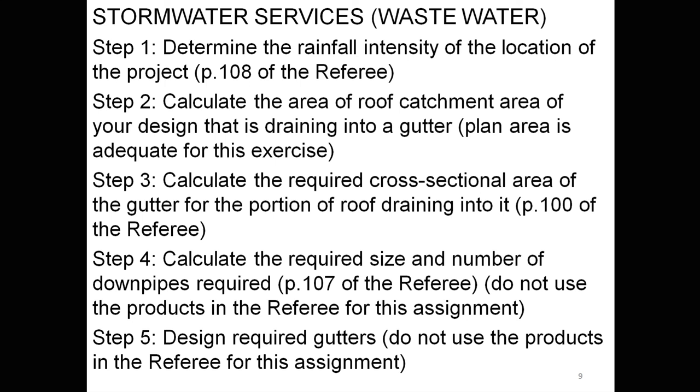I was thinking more in the roof realm up near the gutter. Surely there's an overflow point that needs to be included. No. Especially if it's sitting behind a wall. Put it this way: it comes back to what's going to cause a blockage. You only need an overflow if there's going to be a blockage, because you can essentially design the system where the water will always be able to get away, because you are over designing the size of the gutter, making the gutter bigger according to the worst case rainfall that we get.